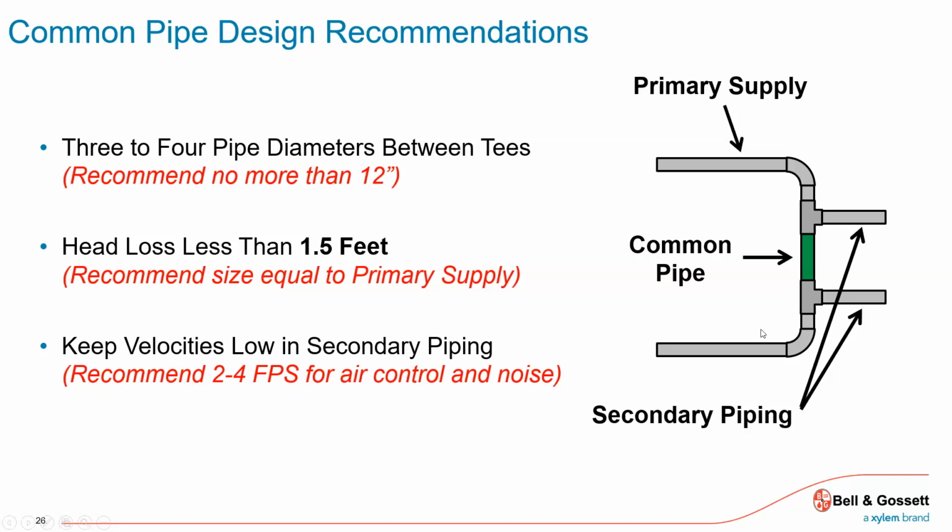As you get into a big chilled water or boiler chiller plant, with, I don't know, 16 or 20-inch diameter pipe, massive, and tens of thousands of gallons a minute, you're not keeping the T's 12 inches apart. That's way out the window, and that's okay, because it's still the same principle. All they're saying is, on that set of T's for that big piping and big plant, at a certain flow rate, try to keep the pressure drop below about 1.5 feet of head. That will achieve that decoupling effect so that I don't get flow where I don't want it unless I bring on a secondary circuit.